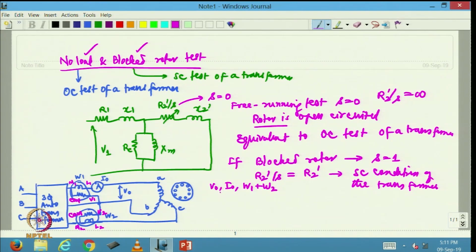Most of the times when I am not going to have the induction motor loaded, I am going to see that one of the wattmeters might kick back, that is I will have the needle of this wattmeter going below 0, in which case I have to reverse the current coil and note down the W1 as the magnitude whatever it is. Now, after the current coil is reversed, I will be able to note down the reading. Let me just note down the reading as W1, but the net power under this condition I have to note down as W2 minus W1, because I have reversed the current coil, I have to take this reading as negative. So, this will be the net power.